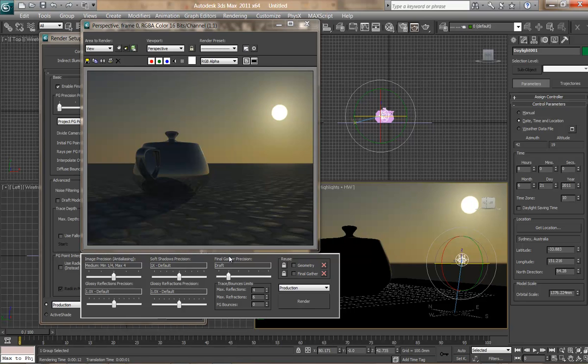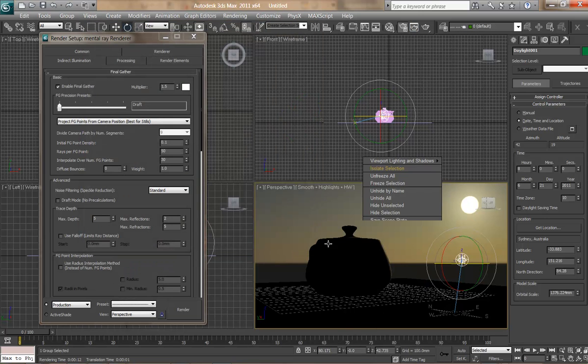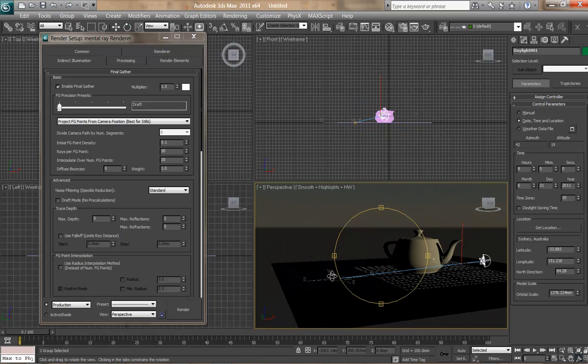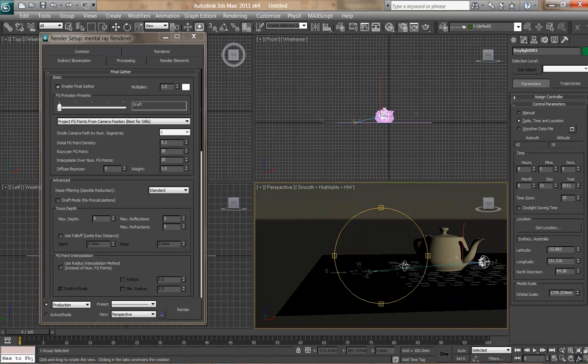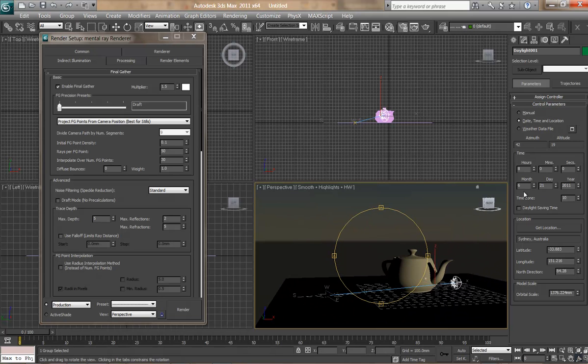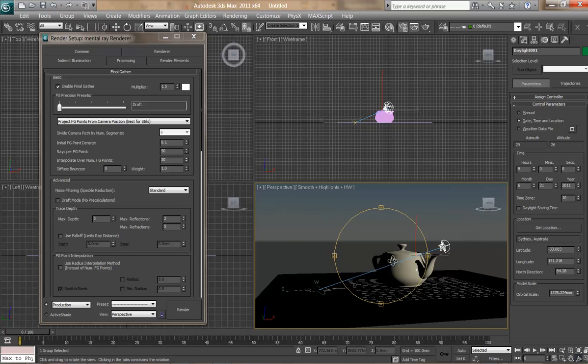Generally, in photography, you want the light source behind. It'll still be at an angle, but you don't want it in front of the thing you're photographing, or your camera. So, even though it's not too bad, the lighting there, and that's all automatic because of the way 3D Studio Max does things. If I bring it around so the sun's behind me, it should be better still. But notice it's quite early, so I'm going to bring the time up. So I mean, early is generally good, but not too early.